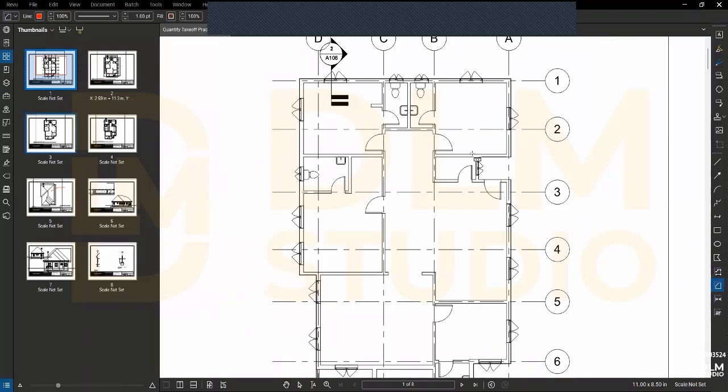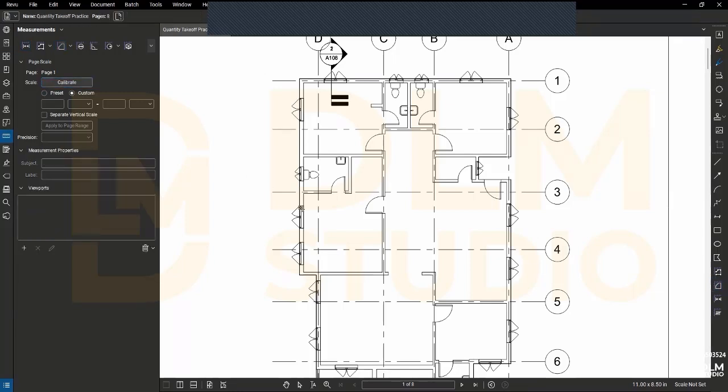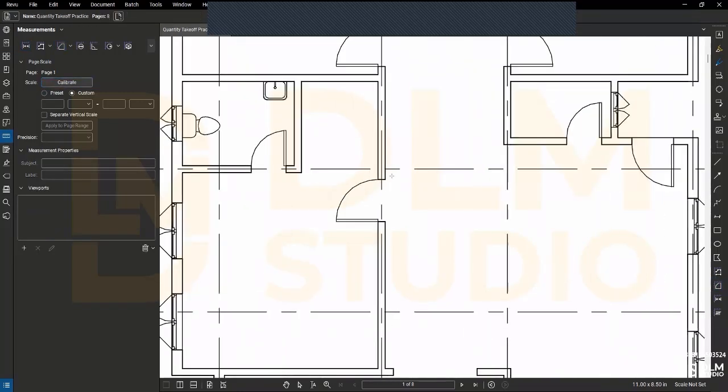Now what we do is use these features to scale our drawing. Let's go to measurement here. Remember this measurement. Now come to calibrate. Once you calibrate, you can just zoom in. Since it's a vector PDF, like I said, it's snapping to this edge. You see, once you get to the edge, you see this blue box. Otherwise, you don't see a blue box. If it comes back in, can you see the difference? So we just pick between this point and this point.